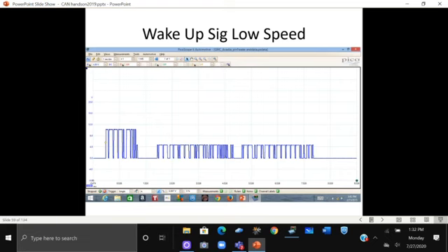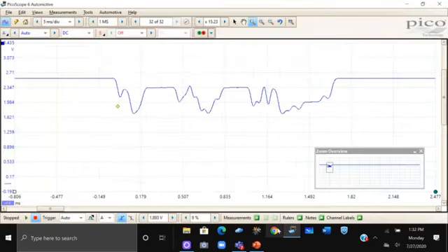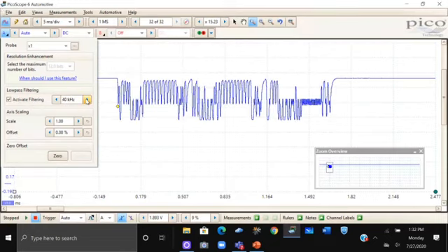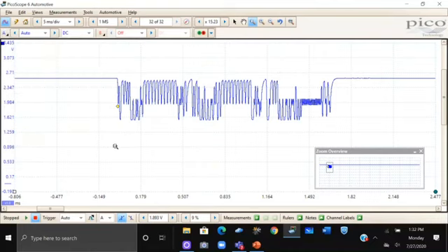Okay, let's go back to Pico, and let's open up. Okay, there, that's a little better in terms of on-off signals. Now, I am on CAN low. How do we know I'm on CAN low? The signal starts high and it goes down.